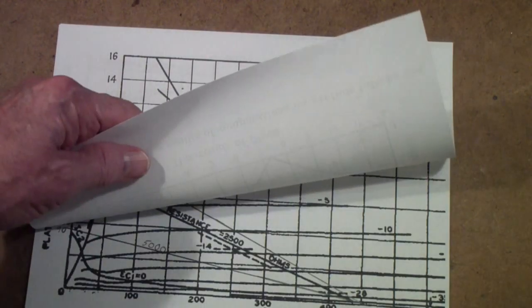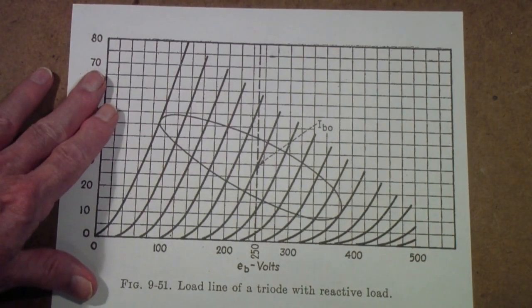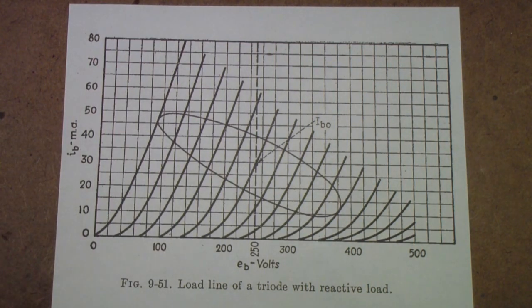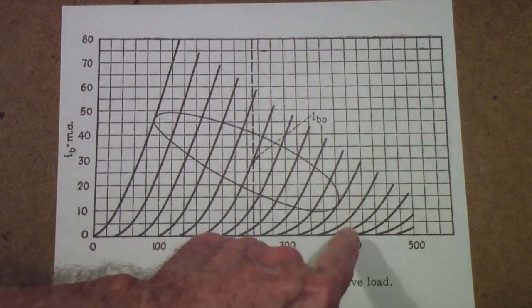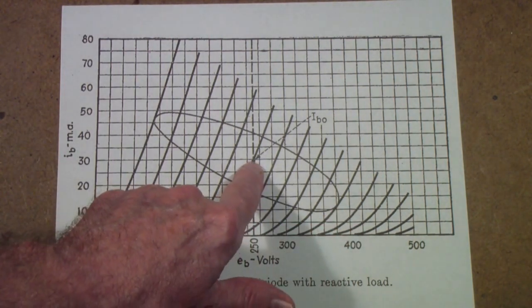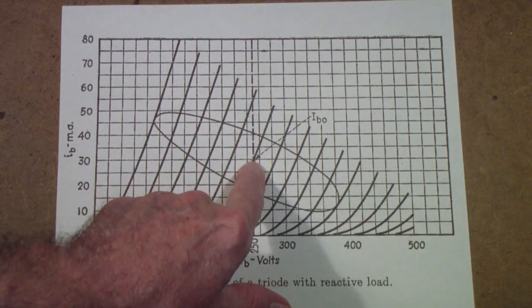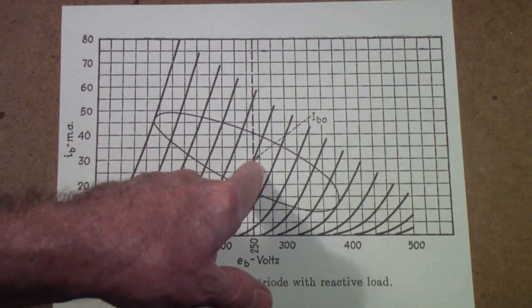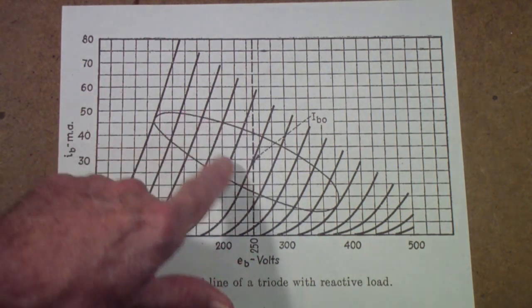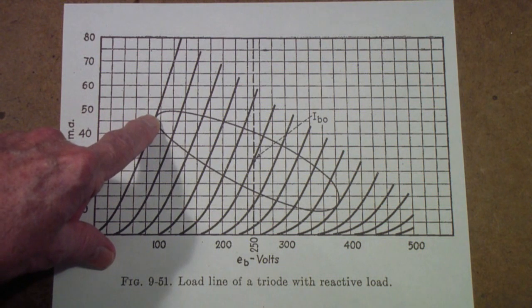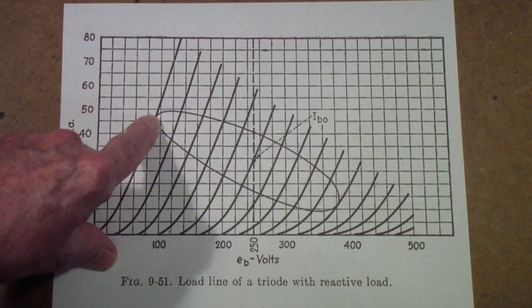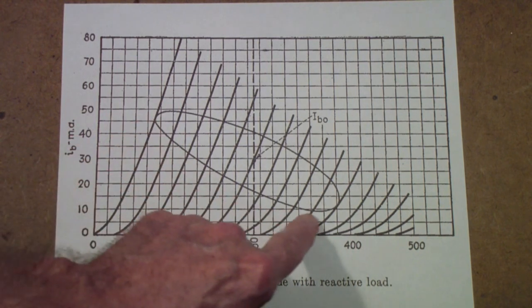So what's the whole point of this? Well, it is that unfortunately, due to hysteresis, you don't get a straight line. You get this. If you have a transformer, this is the load line. In this case, it is for a triode, but it would look the same for a pentode. Notice that this is the operating point. But as soon as the tube begins to put current through the output transformer, you go to this line. So you might go up something like this to this point. And suppose at that point you reverse the current and begin the excursion toward the negative half cycle. Well, you come down this side.